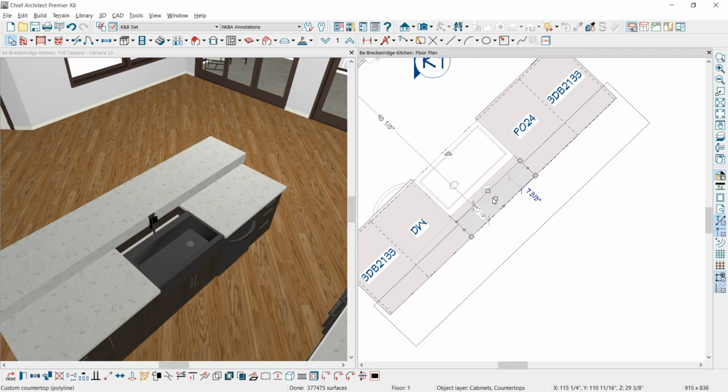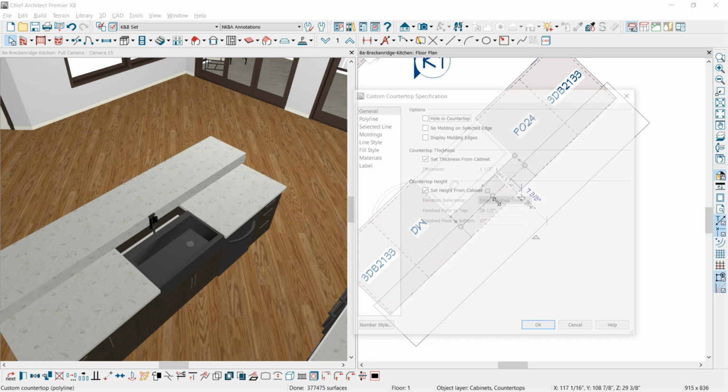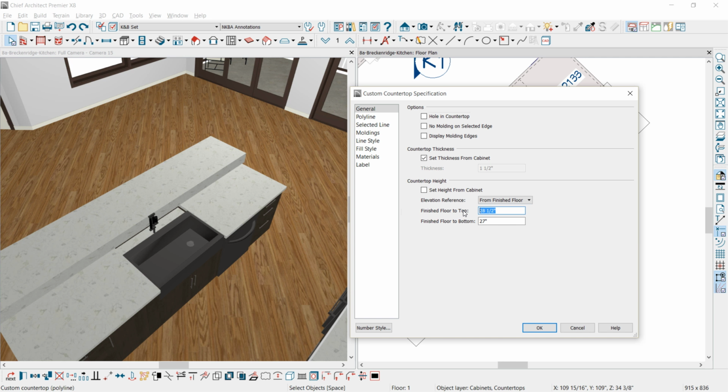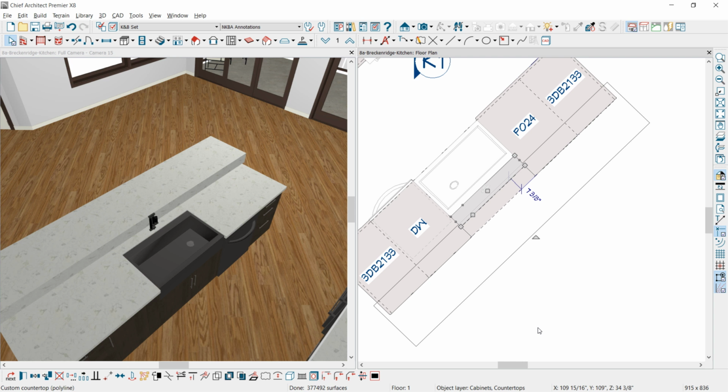And let's go ahead and raise the height of it up after we get it positioned like we did earlier. I'm just going to set that right on that box, and I'll open it and set the dimensions. So inside the dialog, I'm going to enter in 36 inches from the finished floor, select OK, and if we've done our math right, that should set that correctly.